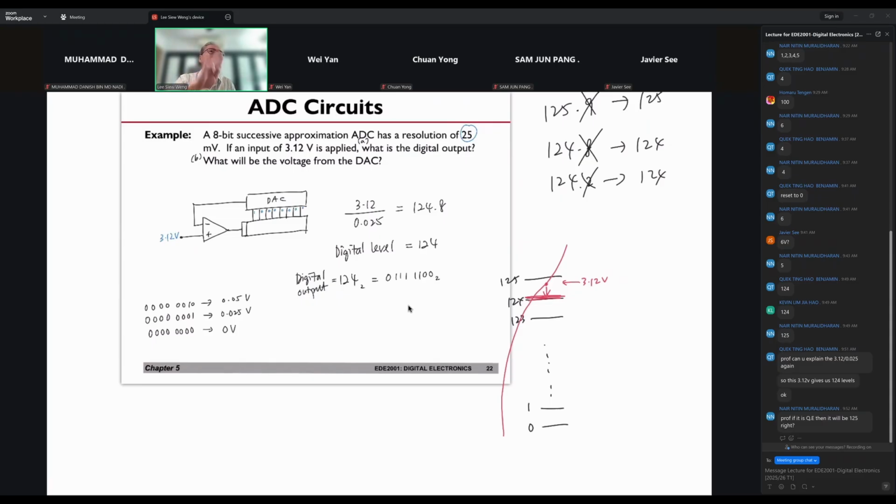Okay, remember, the quantization error that we are calculating is always based on rounding and not truncating. But what we are doing here is truncating. This is the textbook calculation method, and everybody has been following that, because you can design an ADC circuit that rounds down, and you can also design an ADC circuit that rounds off and not truncate. What we are doing is truncating.